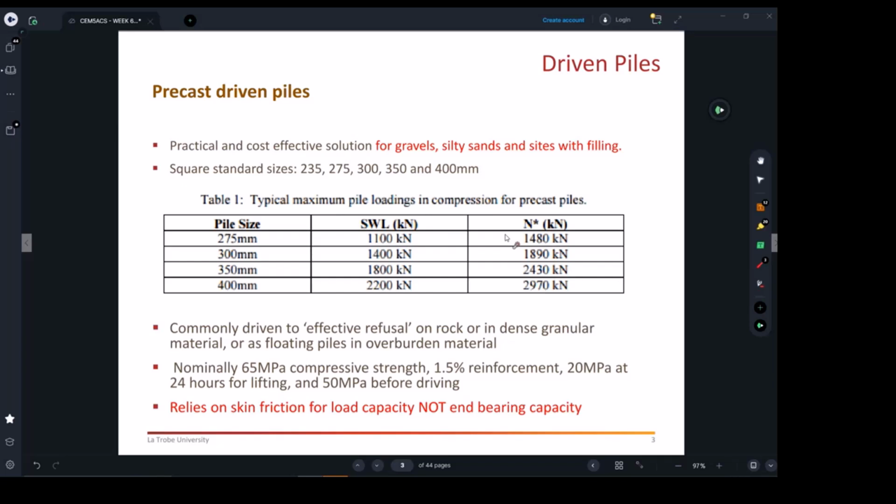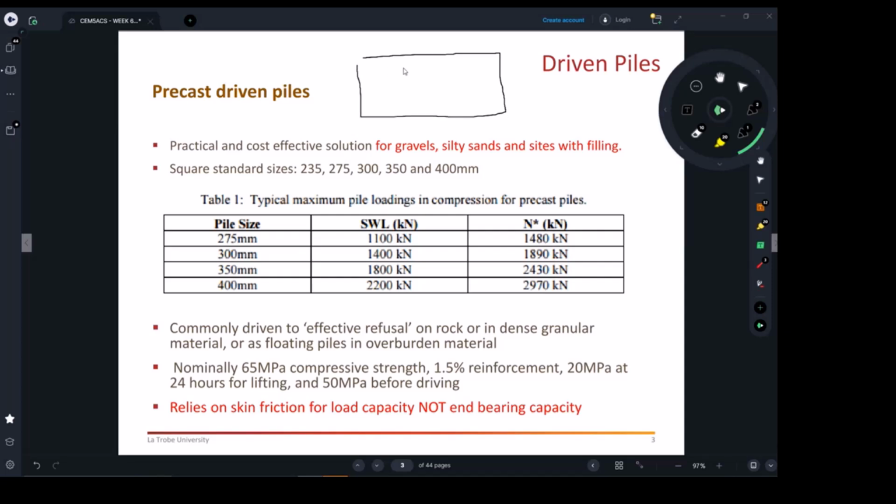Typically in engineering drawings, which I may share with you during the workshop, they're going to show you a pile cap, like a footing plan, and they're going to show you piles as circles, and next to each circle they put maybe P1, P1, P1, then P1. On the drawings, they're going to say to you, P1 should resist this many kilonewtons.